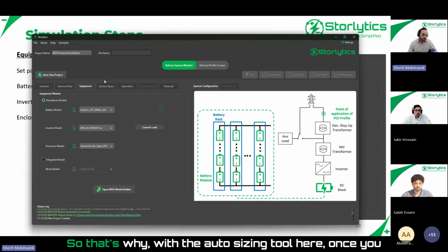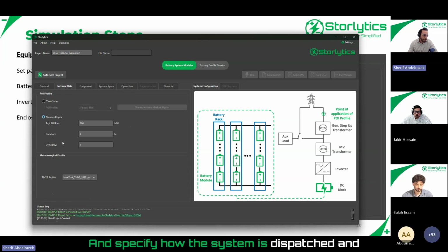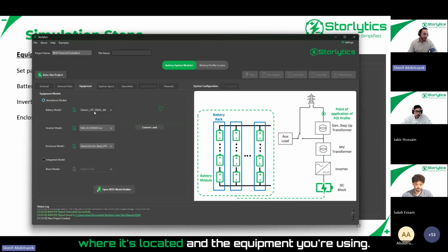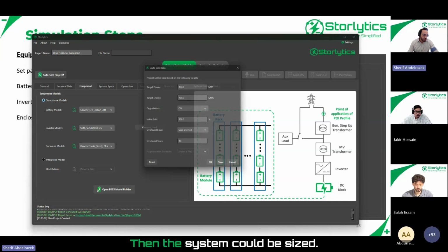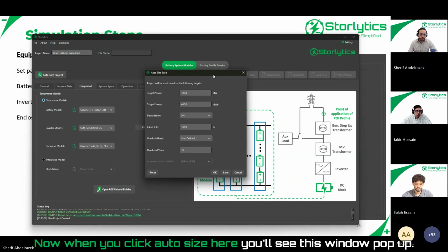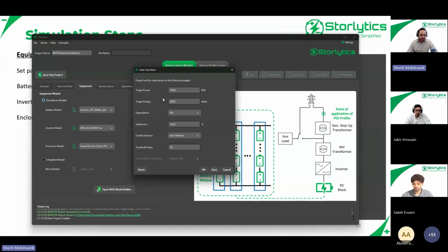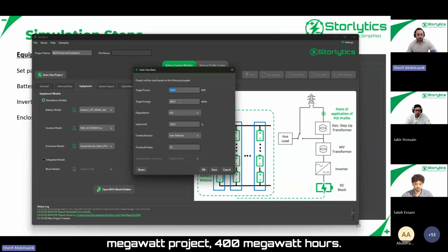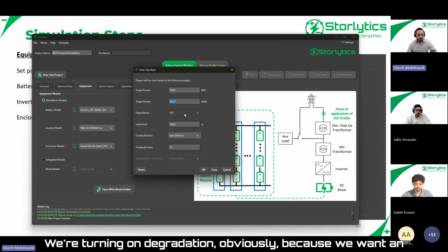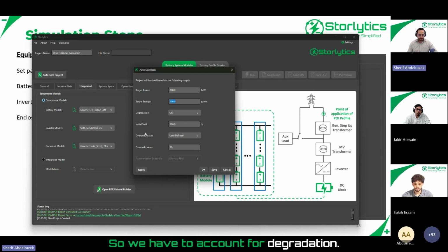All right, so that's why with the auto sizing tool here, once you specify the conditions under the general tab, and specify how the system is dispatched and where it's located and the equipment you're using, then the system can be sized. Now, when you click auto size here, you'll see this window pop up. It'll show you a summary of the inputs you have. So we are designing for a 100 megawatt project, 400 megawatt hours. We're turning on degradation, obviously, because we want an accurate representation of the estimated cost of the project. So we have to account for degradation.